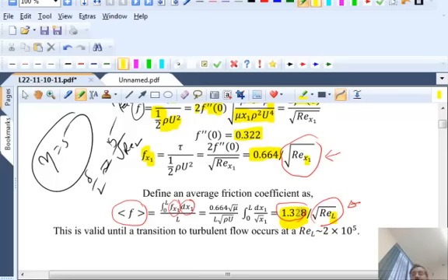Okay, so that's the difference between a local coefficient and an average total coefficient. Now, people have measured the variation of the local shear stress, and I'll show you some of the experimental data later on. How can you measure that? Can you think of a thought experiment to measure the shear stress on a plate? Of course, if it is a steel plate, you cannot do it because it's not going to erode or melt away. You need to find a material that will respond to the local shear stress.